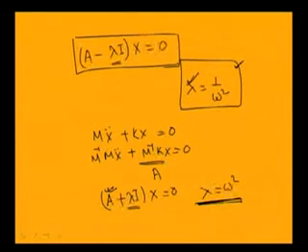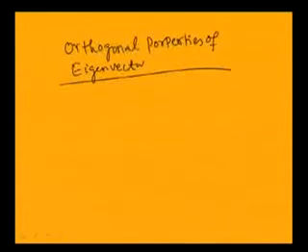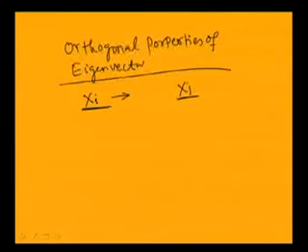For the ith mode, the eigenvector x i corresponds to the normal mode of the ith mode, and x j corresponds to the normal mode of the jth mode. One can show that these modes are orthogonal with respect to the mass matrix and stiffness matrix of the system. Here we are assuming that the mass matrix and stiffness matrix are symmetric matrices.